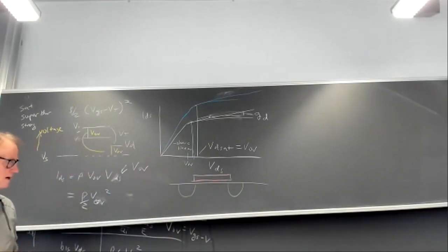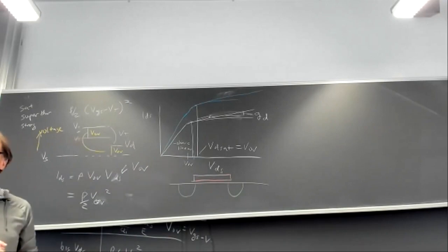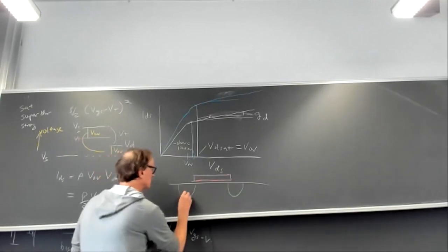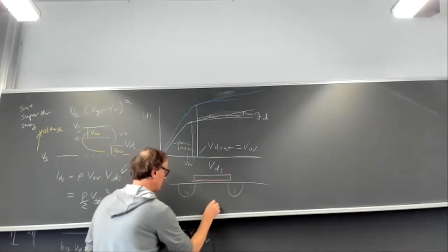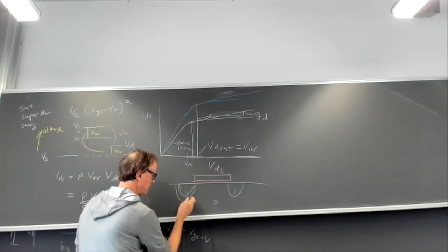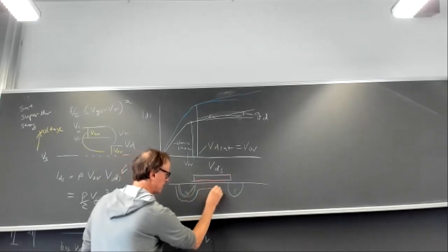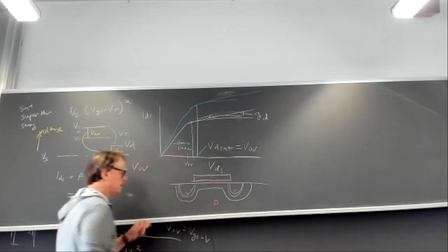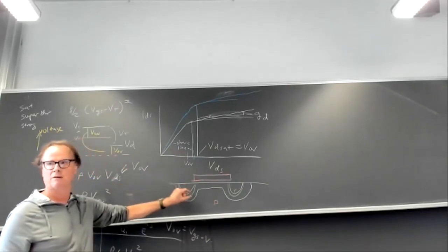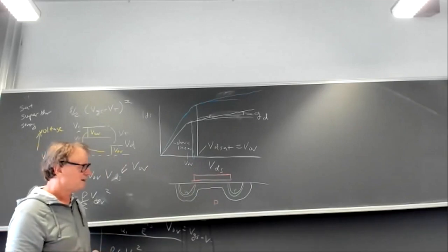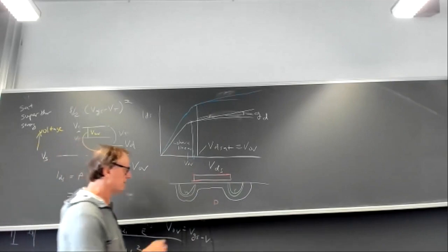Do you remember these depletion regions, these space charge regions you have between every p-n junction? So actually there's a depletion region around these n regions to this p region. I can draw this little depletion region, just draw it like this. It's actually a two-sided depletion region. And when you operate the transistor, of course, there's going to be a depletion region in the channel. There's going to be a depletion region around the drain. And it's a double-sided depletion region. Remember, you have the space charge region where it's positive on one side and negative on the other. Anyway, it's a space charge region where there's no mobile charge, just fixed ions. So, what happens when you increase the drain voltage?